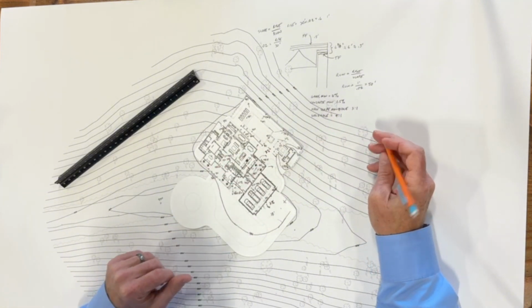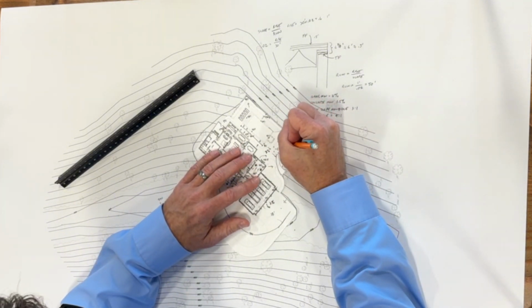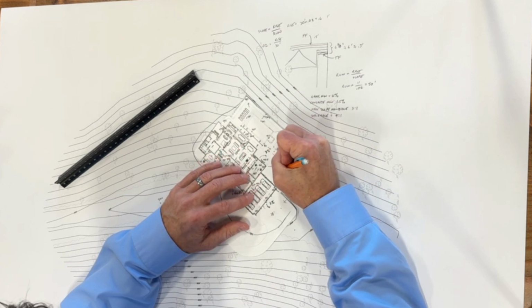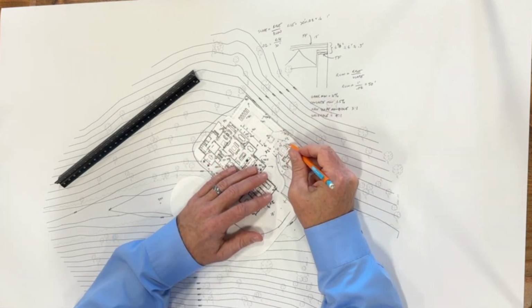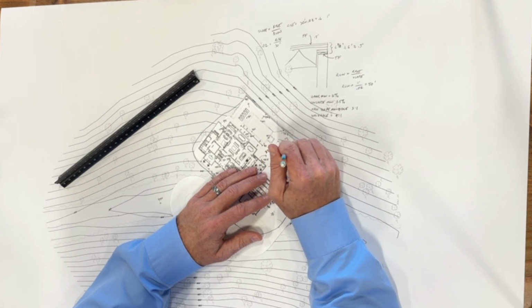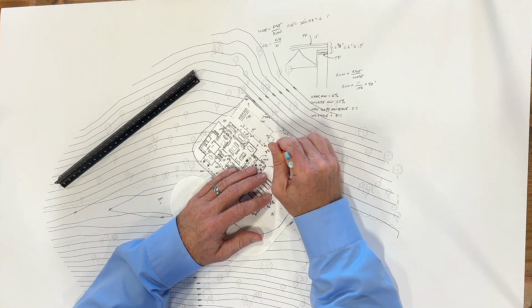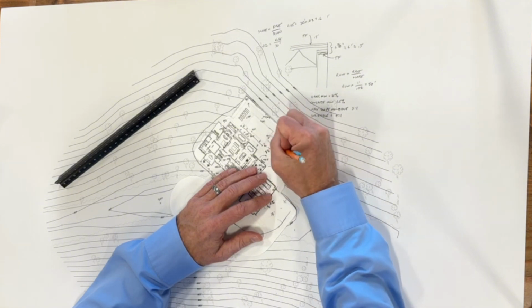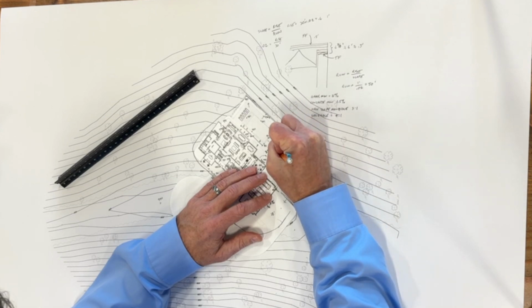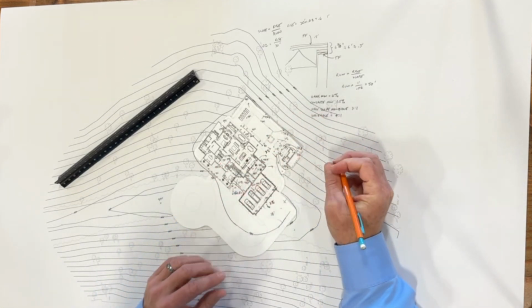Okay, we get that, right? So now as the water is coming down, it's going to go into this drainage area and then out like this. Same thing here. It's going to go this way to the 940, and we pull it in like this so that water that gets blown in under, I know that's a covered roof, right? But it's outside. So water could get blown into here. And so there's going to be a high point right here where the water underneath actually will go this way, and it'll go this way into these two swales that pull it on both sides.